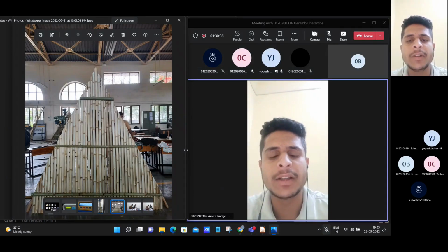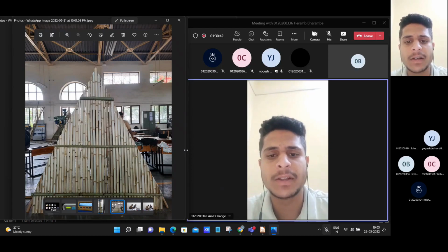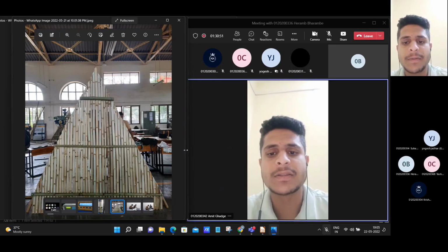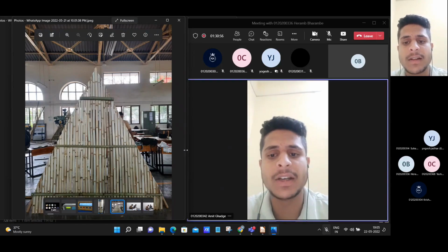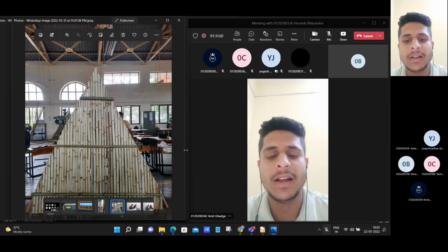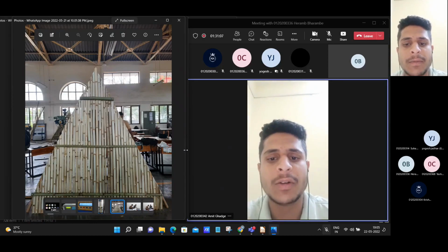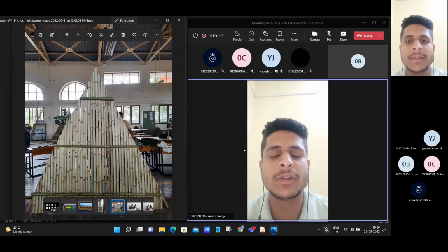All the bamboos are joined together with the help of skids, and the horizontal bamboos are fixed with the help of through joints and keys, due to which they are tightly fixed. The rooftop consists of 50 cross-sectional bamboos placed vertically in a conical slab manner to form the cone-like roof. The whole frame and rooftop are screwed with nut bolts to the vertical bamboos to keep the structure tightly mounted to each other. Make the anchor and strip the bamboo with suitable dimensions.